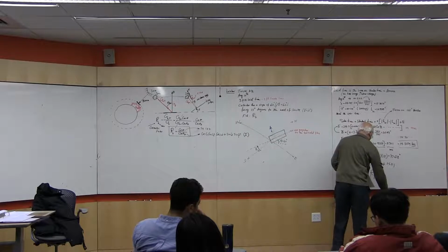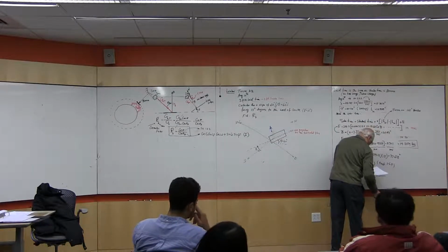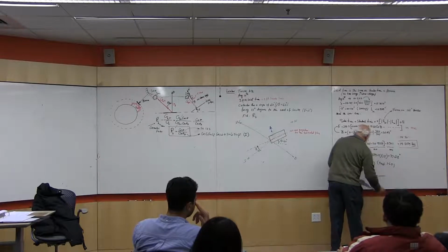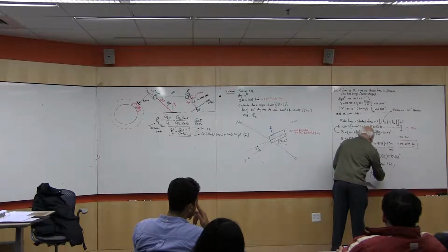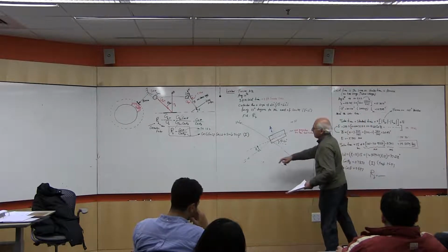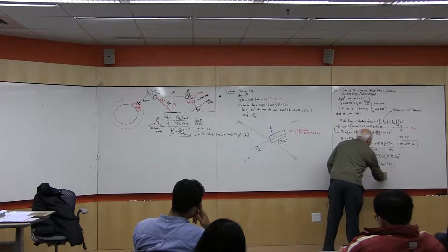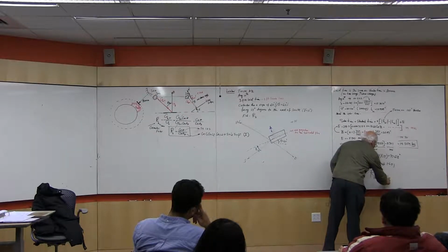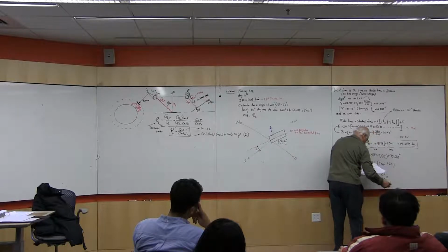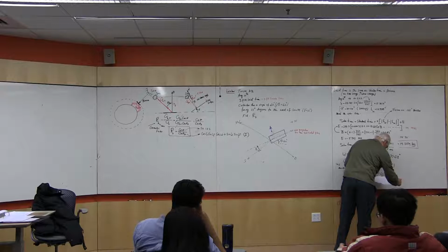So having these two, therefore the last point is that geometric factor of beam radiation on tilted versus horizontal to be 0.8624. So the ratio of these 2, cosine theta, is 0.697 over 0.7873, to be equal to 0.8624.